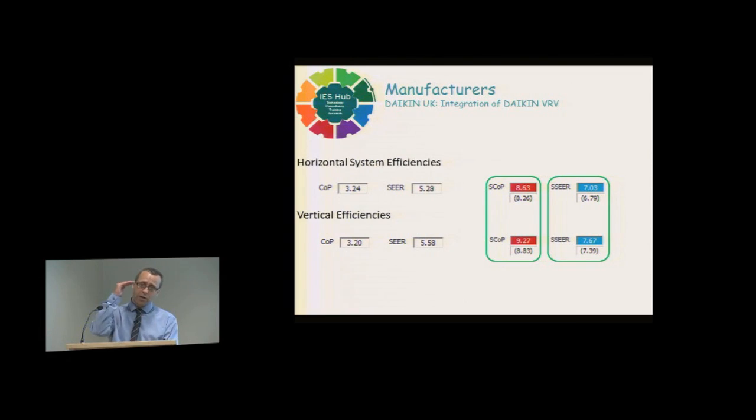I've already gone far too far off the script now to recover. To get above a certain number of floors, in the mornings and the evenings, the stack effect, or the effect of air travelling, warm air moving through the building, means that you can still require heating at the bottom of a building while the top floors require cooling. So you can recover heat between both of those areas, and that effect seems to last a lot longer than the east-west accountability of the systems.